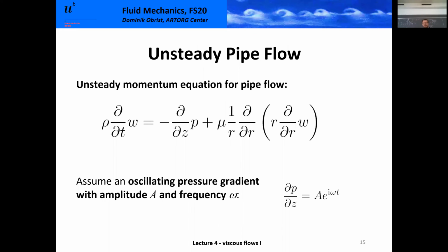Now, the last thing I want to do for unsteady flow is unsteady pipe flow. That is not so different from what we just did. Instead of having a flat wall and an infinite amount of fluid above it with the wall oscillating, we now have a pipe, and confined in the pipe we have a fluid and the pipe is oscillating. Think you're sitting on the pipe, moving with the pipe, then the pipe is not oscillating, but the fluid is. So with this thought experiment you have pulsating flow in a pipe, like the flow you would find in an artery, in the aorta.